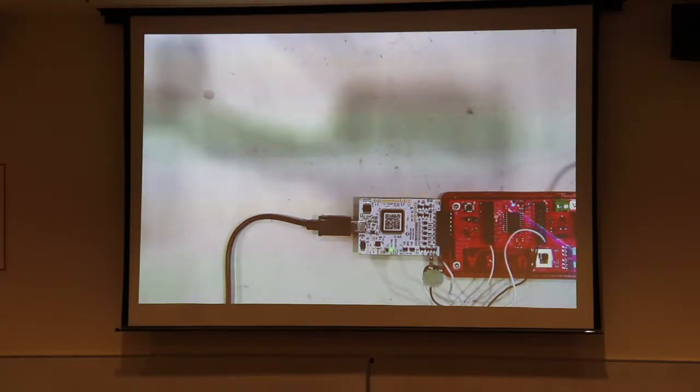If I wanted to do a servo, which maybe I'll show you next week, all I'd have to do is slow the pulse repetition frequency down so that it's about 50 hertz instead of what it is now, probably quite a bit faster. Okay, all right. I think that's pretty much what I wanted to show you.